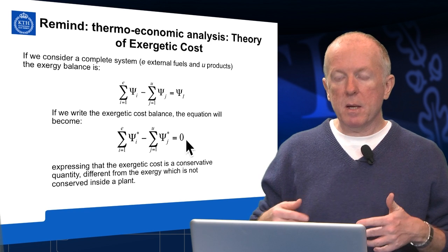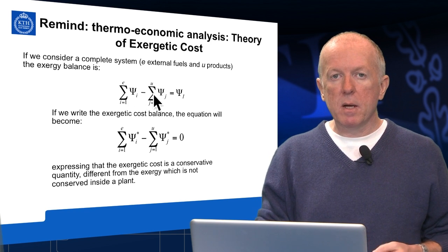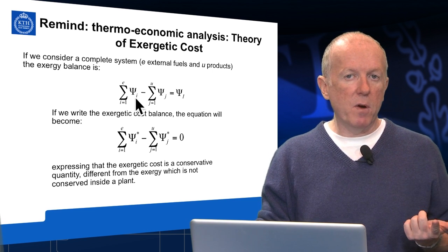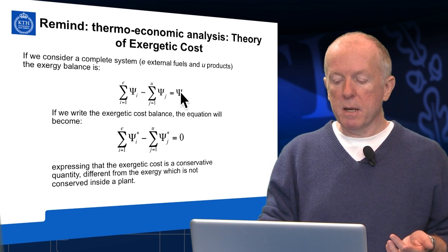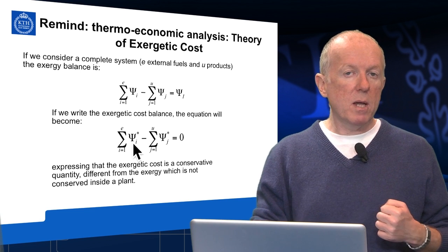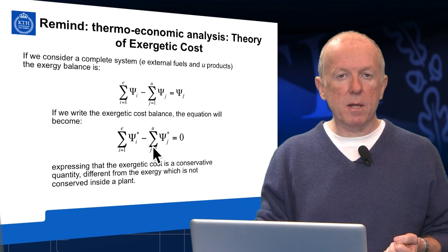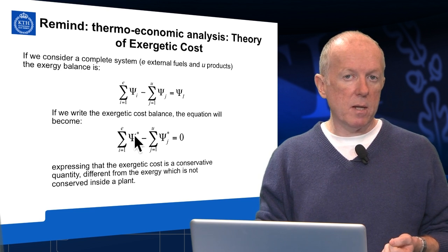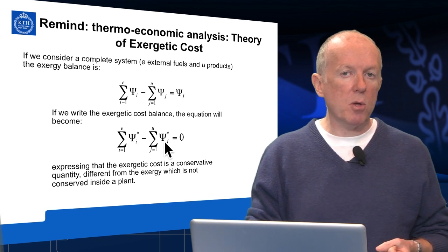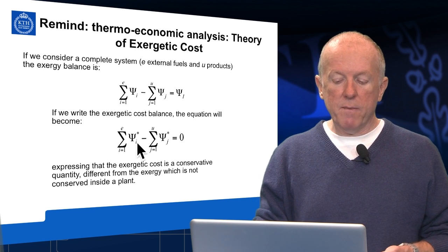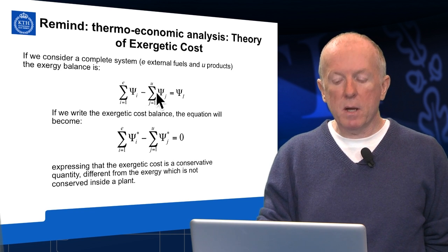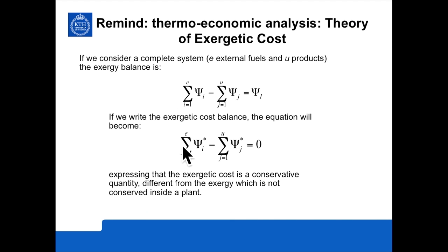So while the exergy flows are not conserved in the system, because part of the inlet exergy flow is destroyed by irreversibility, on the contrary the exergetic costs associated with these exergy flows are conserved inside the system. The sum of the exergetic cost of the inlet fuel is conserved in the sum of the exergetic cost of the outlet product, so their balance is equal to 0. The exergy is not conservative, the exergetic cost is conservative.